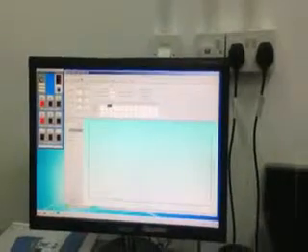Quickly jump to this tuning section. It is more for if you're not getting very nice wave shapes from the material, what we call PID tuning. So we've got what we call proportional gain, integral gain, and derivative gain. It's more for controlling the feedback of the system. So in the standard here, ideally you want to have a nice sine wave loading, and the standard says you've got to be within 10% of the load standard error.